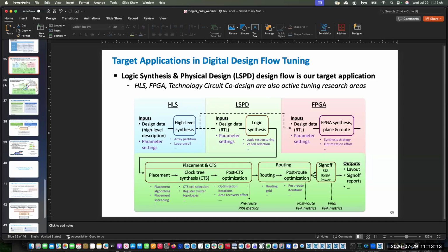So if your example project, the first one, didn't require hierarchy, I might force some hierarchy in there to make you think about how a larger chip would work. It's almost impractical for a large SoC or AI processor to have a single flat hierarchy. You're going to have many blocks interacting, multiple levels of hierarchy. So emulating that might be a good thing. So you would have a starter block, you could optimize it, start to write a tuner, and then force some hierarchy in there to get a chip level understanding.